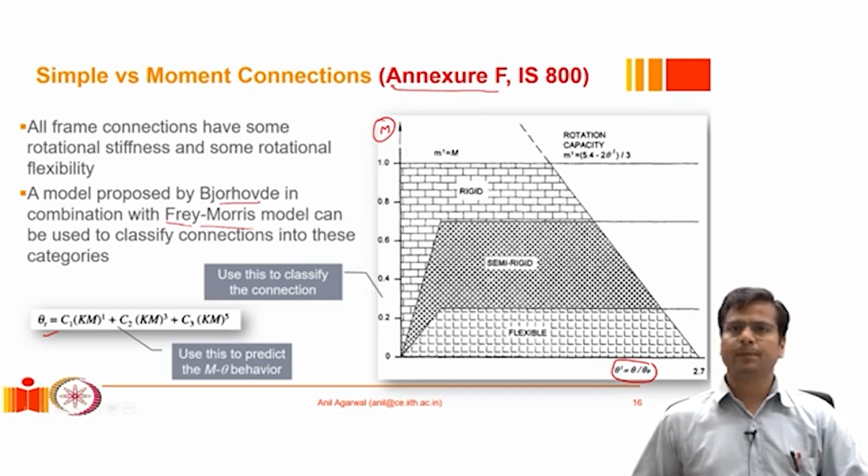However, in reality, it is not possible in a design office to do all that calculation. It is okay to develop one type of connection by using this method, but for day-to-day practice in a design office, it is not possible. Therefore, every design office has a few pre-defined connections that they prefer to use, which they have already verified or somebody has verified, and they know that the connection falls in this category. So now we will talk about some of those commonly used connections.